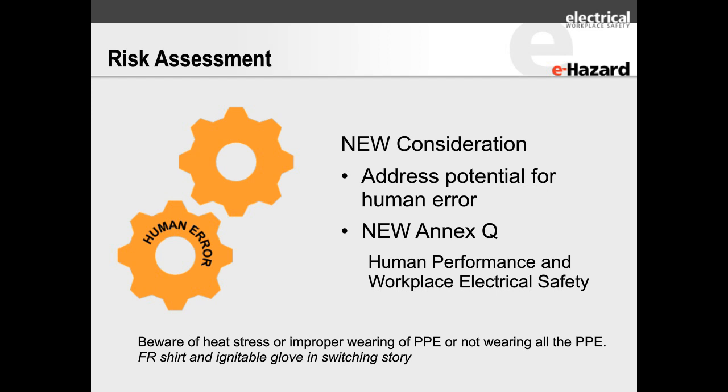One of the things we like to bring out on PPE is you want to be careful about PPE. One of the things about PPE for 70E that's different than most PPE settings: most PPE is sort of protective. If you look at flash fire clothing, it allows 50% body burn in a very specific burn, whereas with arc flash clothing, we allow it only to cross the second degree burn. We don't allow anything to cross the third degree burn in our calculations of the ratings, but when you're using it, it's almost like a smart PPE.